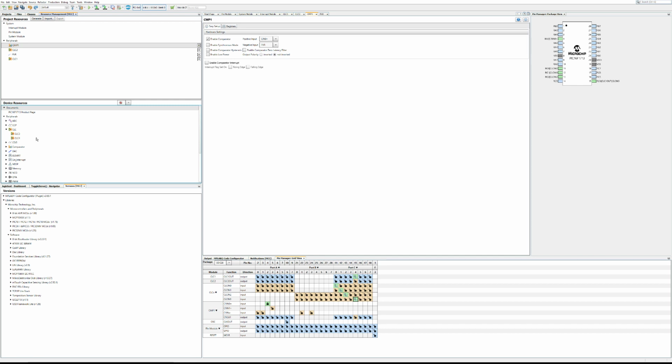So that's a simple way to more intelligently decide whether you need to wake up the CPU in a certain situation, or if you want to still provide manual control over some feature even without turning the device on properly. Or in many applications you may never need to turn the CPU on, so you're only using these logic functions. So it can be quite helpful. So that'll do for the comparator.